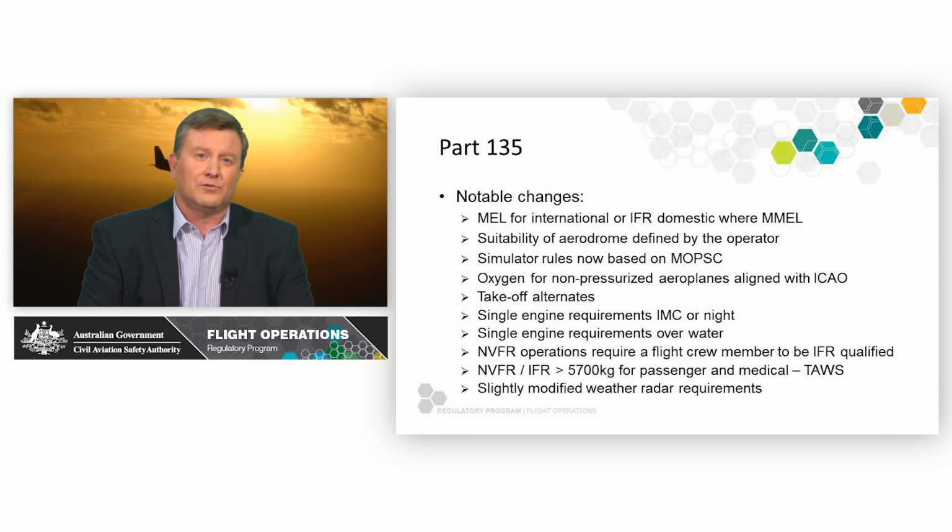The simulator rules are now based on MOPSC, which is a term that underpins the delineation between parts 121 and 135. It stands for maximum operational passenger seating capacity. So it's the maximum seating capacity that you've decided to have on board your aeroplane. That can be, if you choose to do so, different to the certificated seating capacity that comes from the manufacturer.